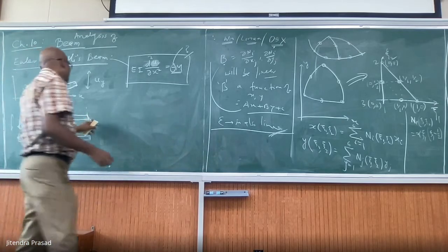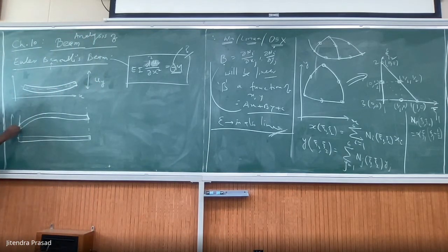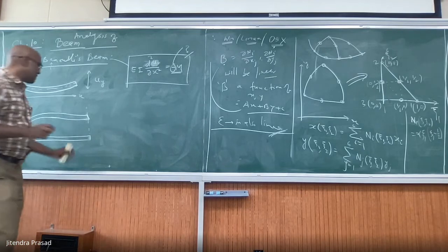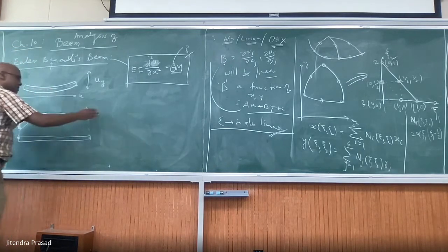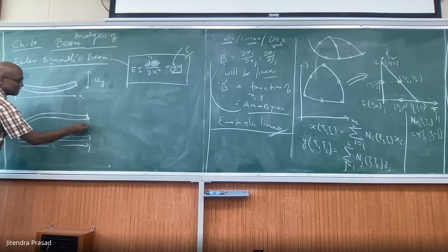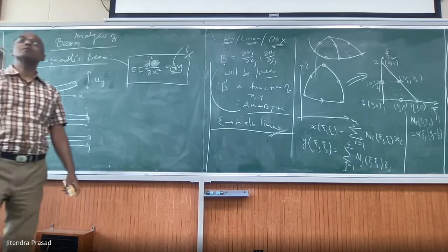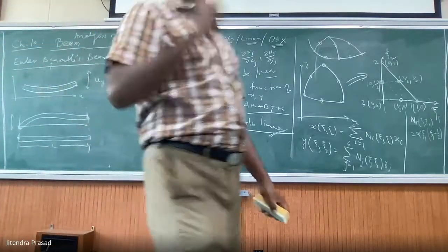We have to look at the end. What it says is that the middle point of the section is just right above it. So meaning that length does not contract, for example. It remains the same. Total length, whatever L is here, if we measure midpoint to midpoint, this will be L1. It is not going to contract. This is the assumption in case of a beam.